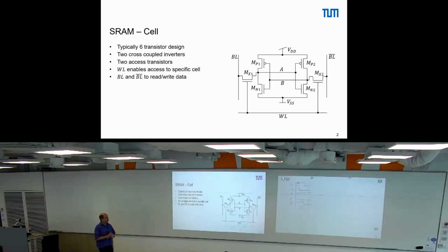So what actually happens? I correct this: our preloading you can do with 0, and you can also do it with VDD, by the way. What you do in practice is you set it to VDD half. So we set it here somewhere in the middle, both sides. Now we enable the word line. So what happens now?